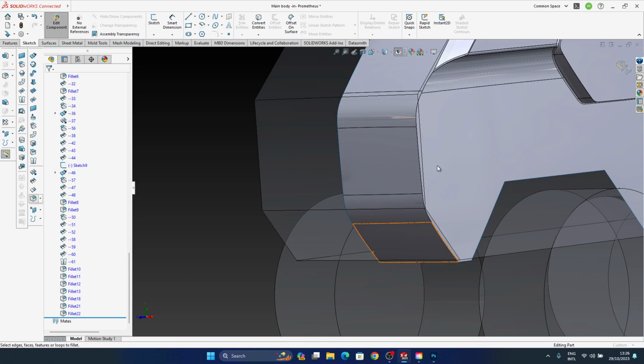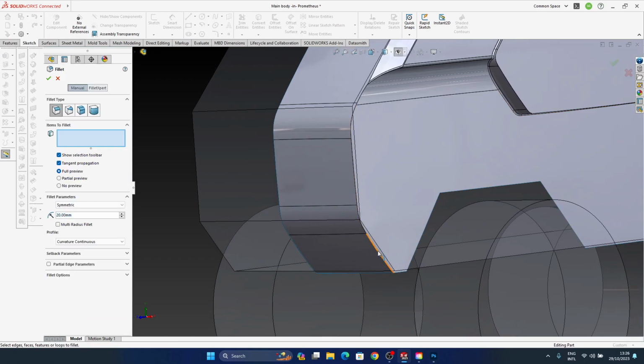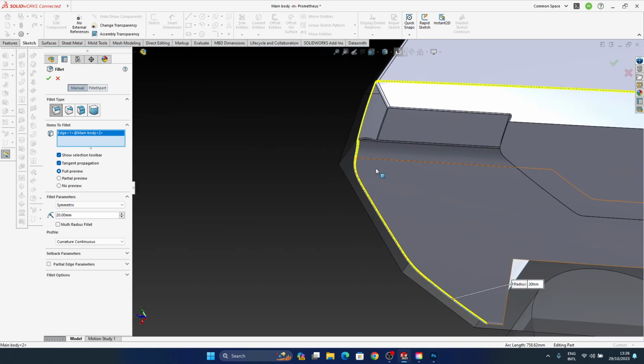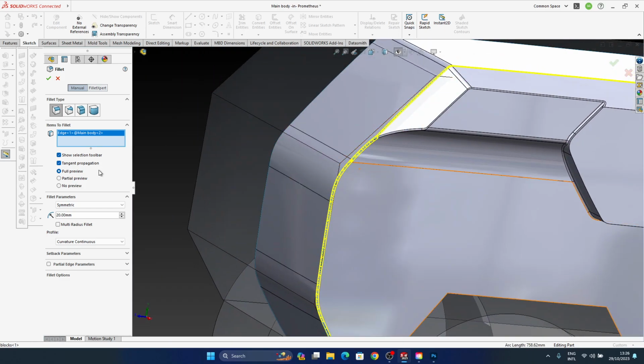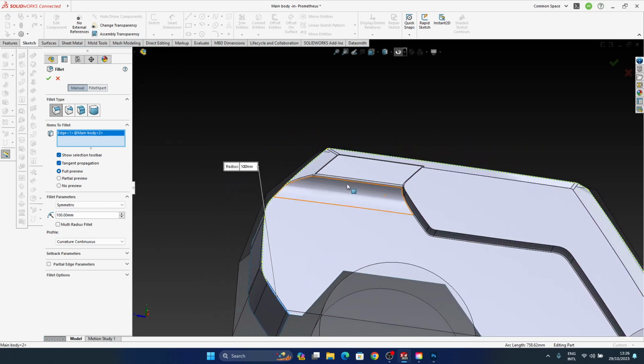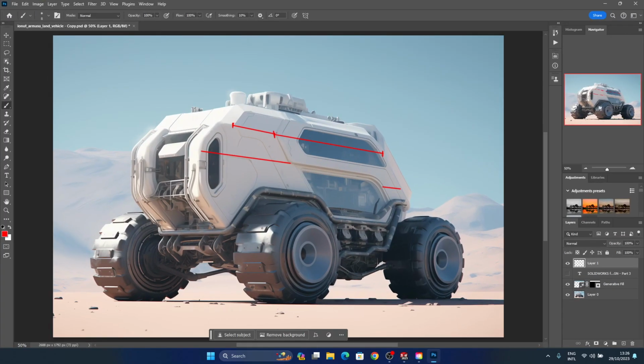So if I am just going to make another fillet to check now how all this will contribute up to the end, because I am having a bigger fillet in there towards the front. So if I'm saying 100, most probably it will say no, I cannot build 100, which is fine because I'm having a bigger fillet in here, but here it's sharp, it's not big anymore.